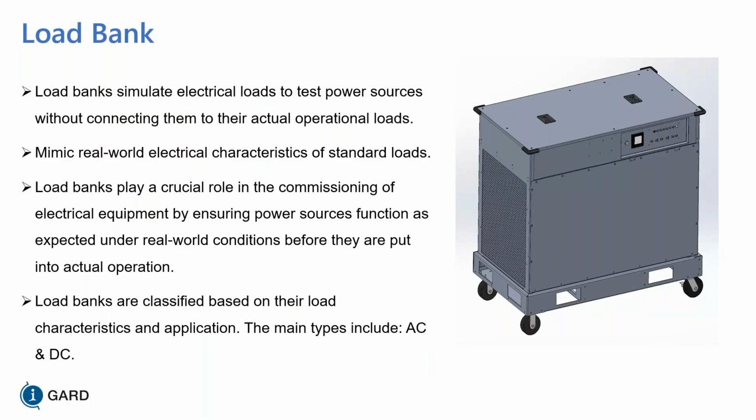So if you look at some of the testing requirements, which you're going to see later on, some of these test requirements require 3 hours of testing. And you may not be able to guarantee that you can maintain 3 hours at a certain kVA or kilowatt. So that's why you need a load bank. And you have to do it according to NFPA 110 and some other standards.